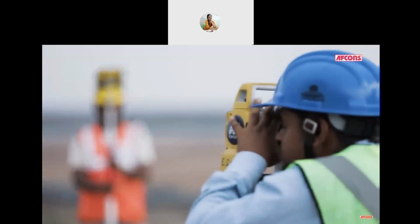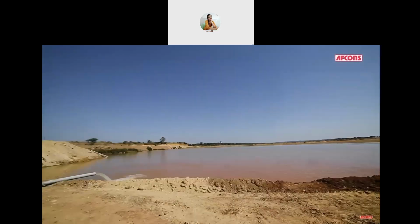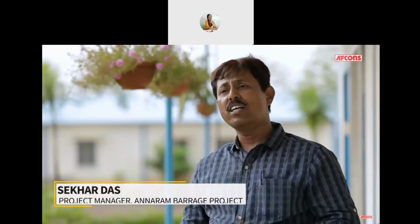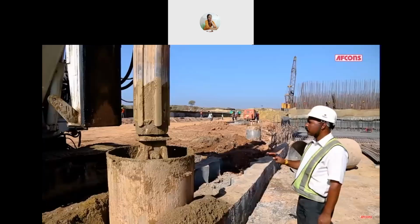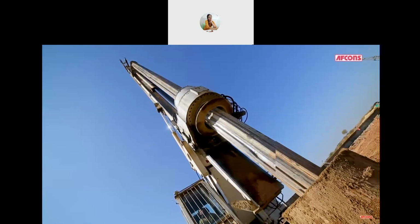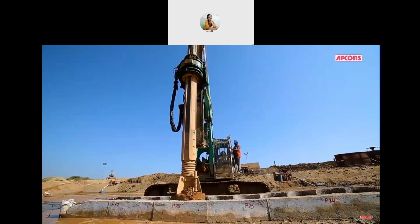The new geological survey threw up another challenge. The ground at the new site had differentiated strata. In the geological investigation, it was found that we are encountering different strata under the ground. It was sand, then even silt soil, and gravels and hard rock. With these types of changes, a sheet pile is not possible to drive. So I've changed this into secant pile. The client decided to use secant piling in the cut-off foundation for the first time in the world in the construction of a barrage.